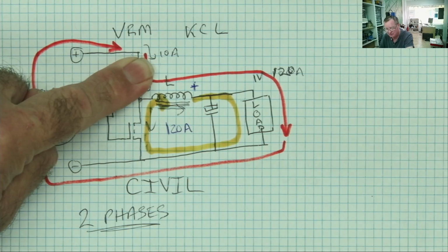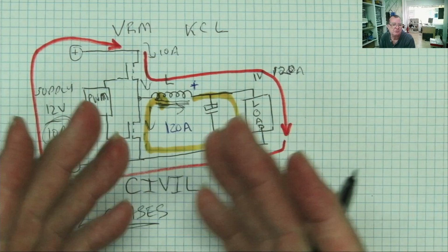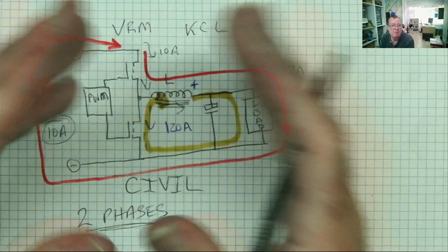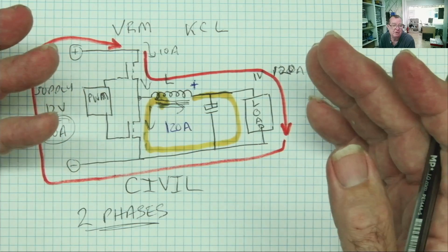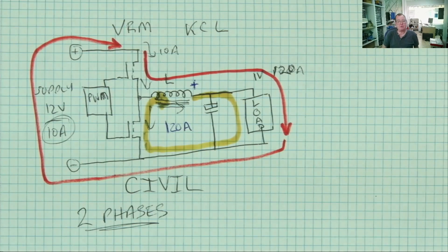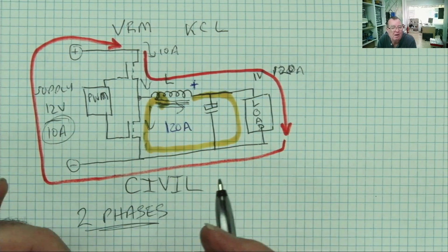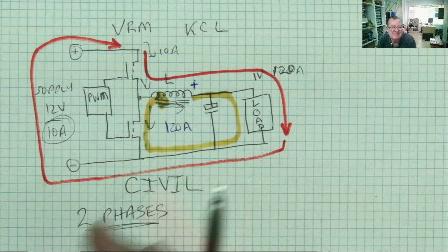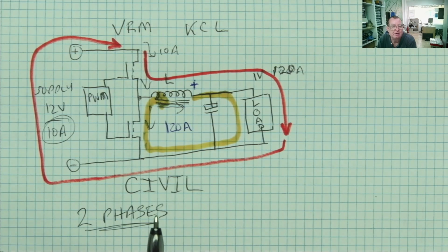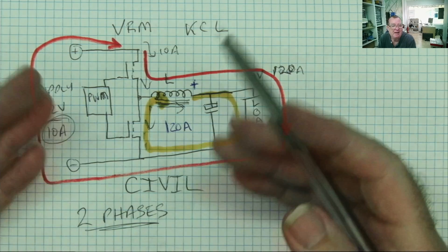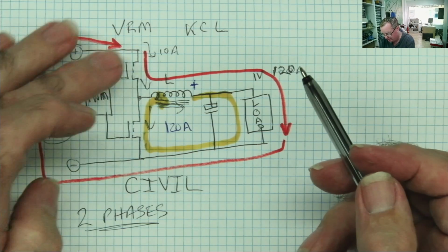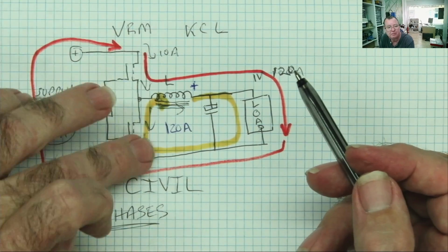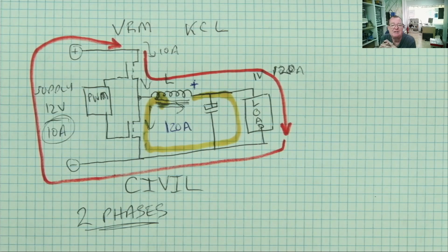Okay? So what we actually have here are two circuits. Although it's all interconnected, from Kirchhoff's point of view and from the circuit operation, we have two circuits. That's why it looks initially like it isn't obeying Kirchhoff's current law. It is. It's just switching so rapidly between the two circuits by switching these on and off. Maybe your mind can't think fast enough to realise that's what's happening. Okay?